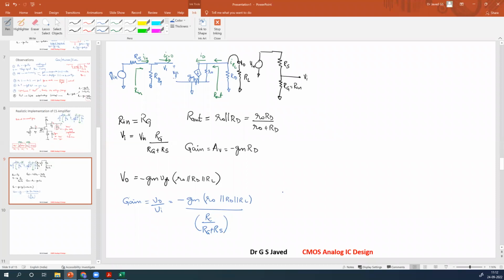So this, when you rearrange, correct? Is this correct? It's wrong. This is wrong. You see the gain Gm AV, right? So what is the total gain? It is Gm times R0 in parallel with RD. So now you will get the total gain to be, total gain is from V in to Vi. So this is a gain factor, right?